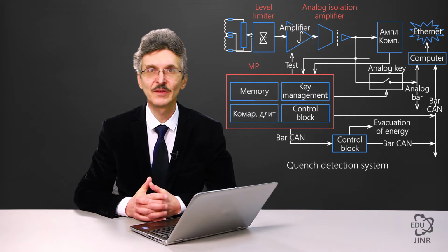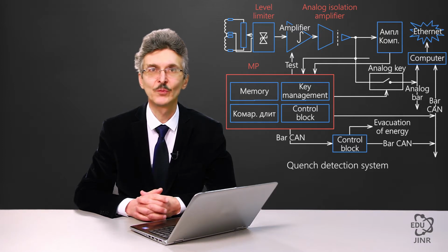The signal of activation of the energy evacuation system has to be given in case the off-balance current exceeds some threshold value, predefined by the operator, and in case the duration of this excess is longer than the predefined threshold time. For fine-tuning, the detector should allow remote control of these parameters. The Nuclotron has around 200 such detectors, pairwise connected to magnets and quadrupole lenses.